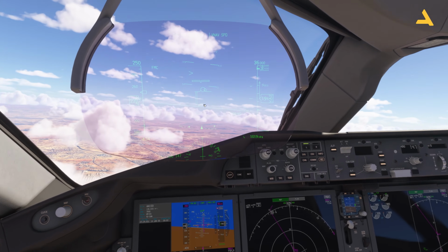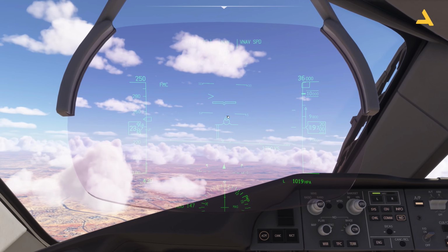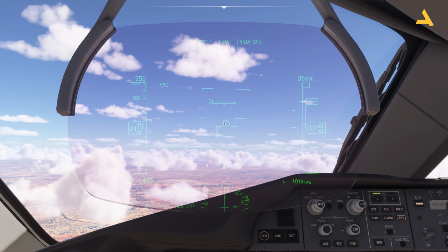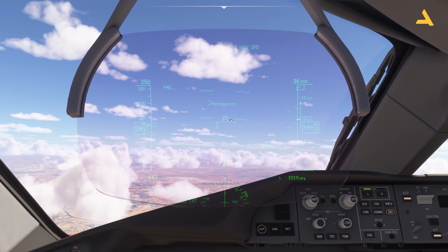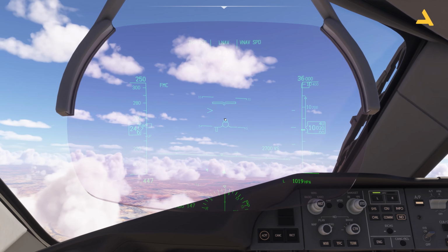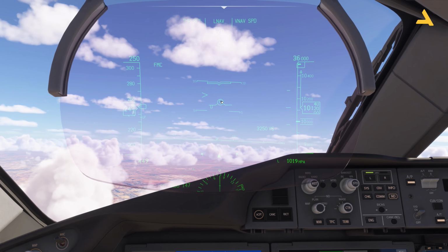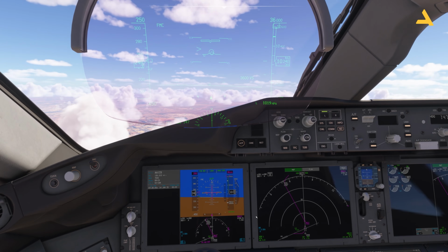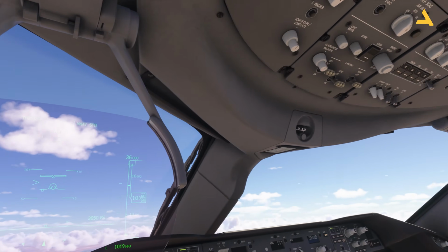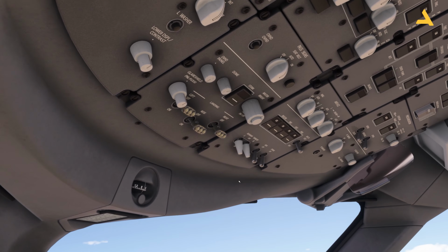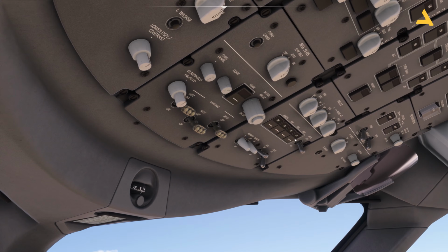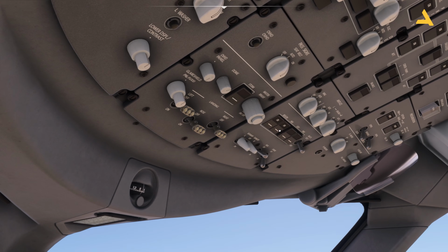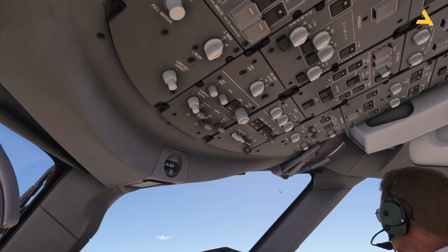This small circle shows you the flight path, and this is your flight director, so you have to keep this small one in the middle. The autopilot is actually doing it, but even if you're flying it yourself, you have to make sure that it remains in the middle. Now as the plane is above 10,000 feet, I can turn off the lights. Only strobe, nav and beacon will be on throughout the flight.